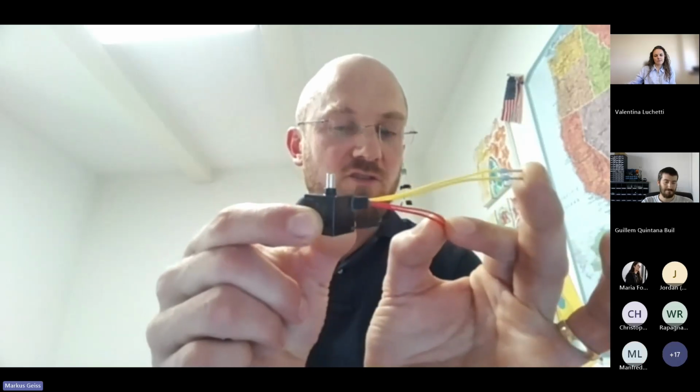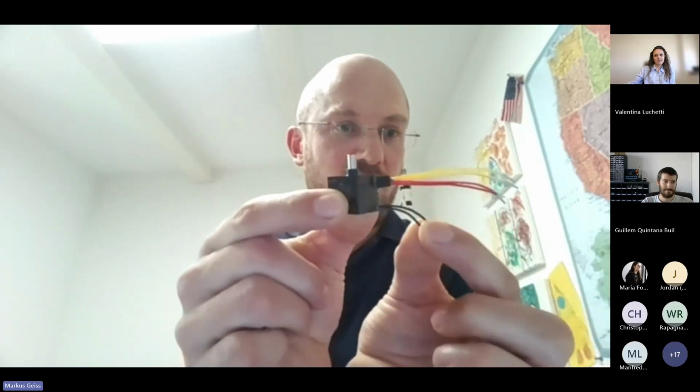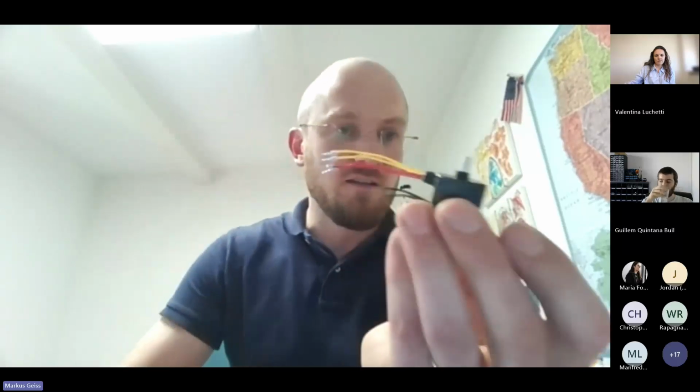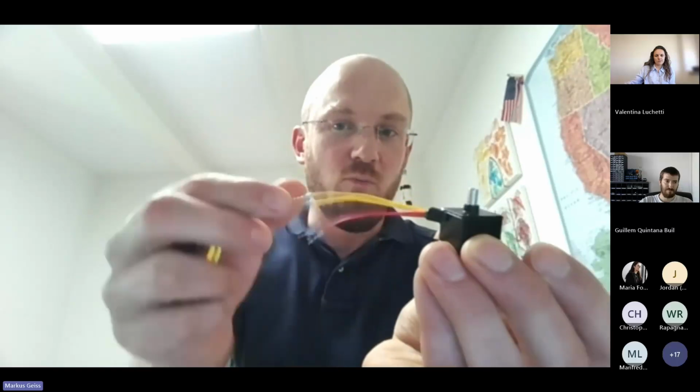And here it is. This is our nano pin puller. It's a shape memory alloy-based release mechanism made out of 7075 aluminum with hard anodization. It also is fully redundant, so it has two independent trigger lines and it has telemetry. So with this little actuator, you can sort of launch anything and lock anything in shear, ideally. Once it releases, the spring-loaded mechanism that you have applied this to will open.